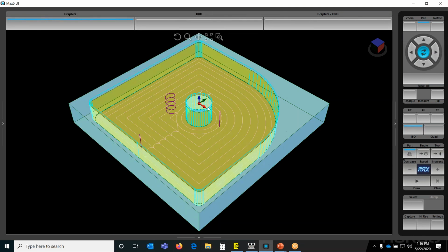So this here is just a standard pocket, nothing more than a mill frame where I put in some different corner radiuses just to show some different geometry so we can kind of see how the AdaptiPath reacts once we turn that on. And we have an island here in the center, again, just to kind of force some different motion out of the software.